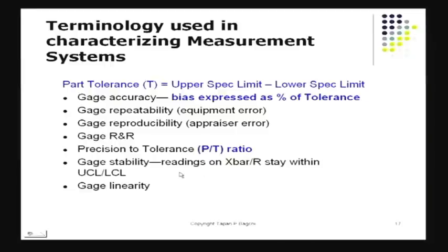Then of course, if I'm using a system that can shift its performance over time, I may produce some control charts, and that is to be done with some standard objects. I may take some standard objects and measure their dimensions at various points in time, and produce a control chart with this. The control chart can tell me if the measurement system itself is drifting or if it is staying stable. That's something I can do quite often by plotting various types of control charts. It's a pretty decent approach to make sure that the system stays the same as time goes by.